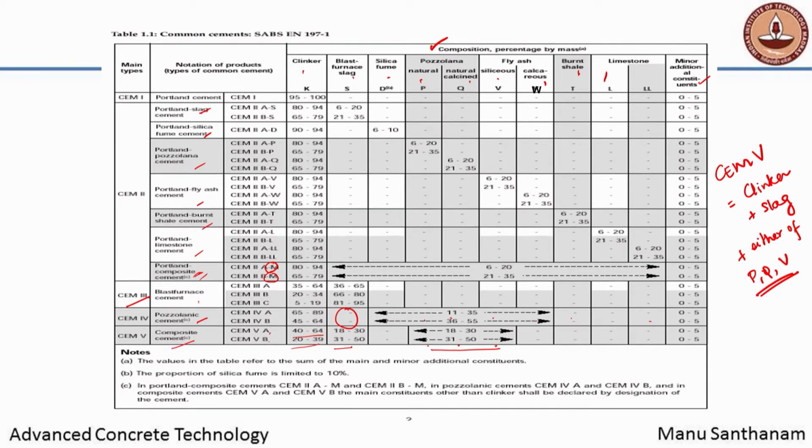F fly ash. Now, if you look carefully in the Indian standard also, there is a new standard for composite cements. I am sorry I do not have the number right now with me, but if you look up the Indian standards, you will also find you have a standard for composite cements where they allow you to have a ternary blended system with cement, type F fly ash and slag. Okay, that is a composite cement standard as per the Indian specifications, and you will probably be able to see it if you browse through the Indian standards. Okay, it is a recently released standard.